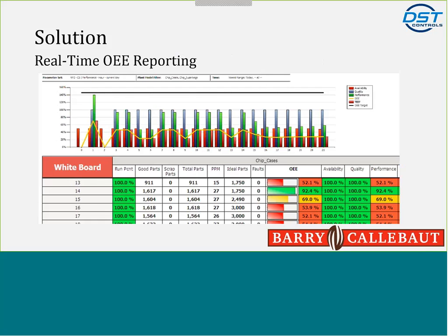Now, this report is showing all your OEE numbers rolled up into one high-level view, and this is showing your availability, your performance. Your OEE is the yellow line here, and you can see how OEE is bouncing around right around 40%. But I find this interesting because these are hours and this is a day's worth of data, and you can see if you look closely that green performance line varies quite a bit. In the morning, they were doing quite well, and they got on a good run, but then in the afternoon, the performance really started dropping off, and that had an impact on the overall OEE number for that machine for that day.